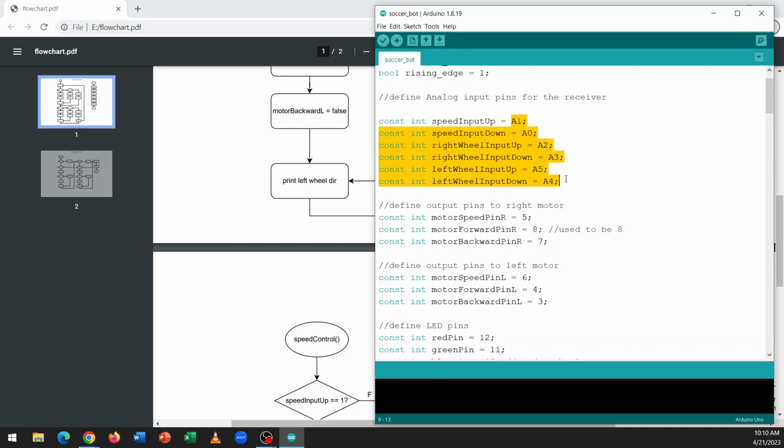And as you can see, we are using the analog pins because we ran out of digital pins on the right side of the Arduino for other purposes. So we're using the analog pins, but we're still using them as digital inputs, because analog pins can also still do the digital input pin functions. Okay. So again, these are the input pins that the Arduino uses to receive signals from external electronic components.